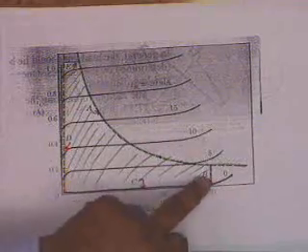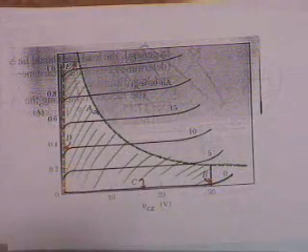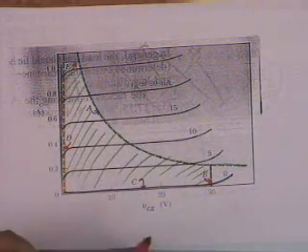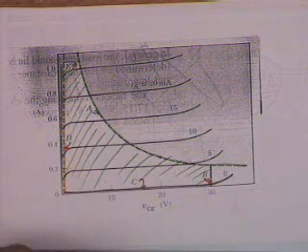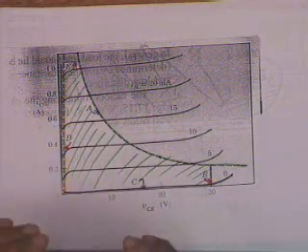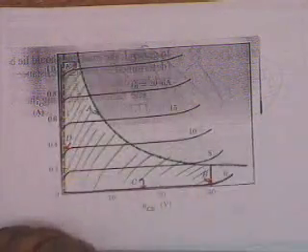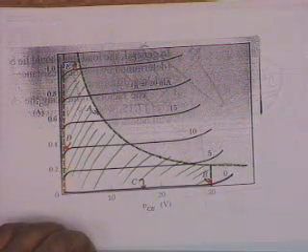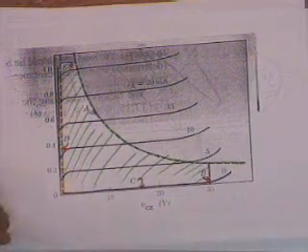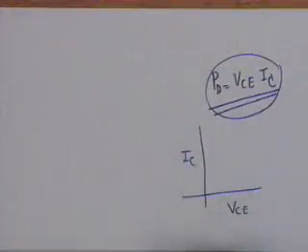And therefore you have a completely bounded region within which you must operate the transistor. The question now is, is this point clear? That is a completely bounded region? It's bounded by 1, 2, 3, 4 straight lines and a hyperbola. The hyperbola is the so-called power dissipation hyperbola, that is VCE times I sub C is a constant. The question now is, within this region, where should your Q point be? Where should the operating point be? And for that, I shall project another diagram.